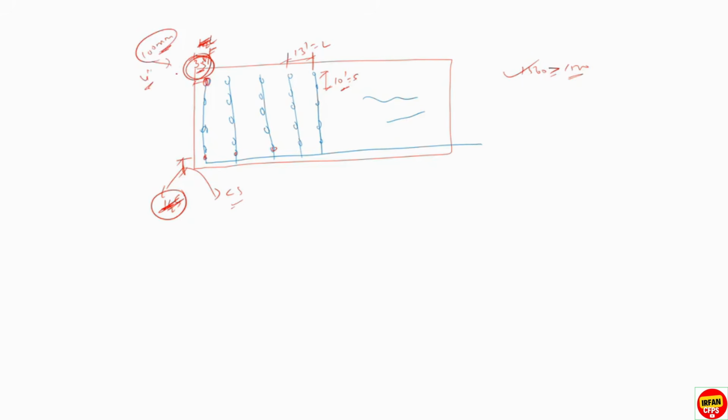This is in mm. 4 inch you can consider minimum from the wall. Minimum distance from the wall to the sprinkler is 4 inch. Maximum will be 2.1 meters. But in the previous example, we considered half L and half S, and then we got 1560 square feet, which is more than the 1500 square feet design requirement.